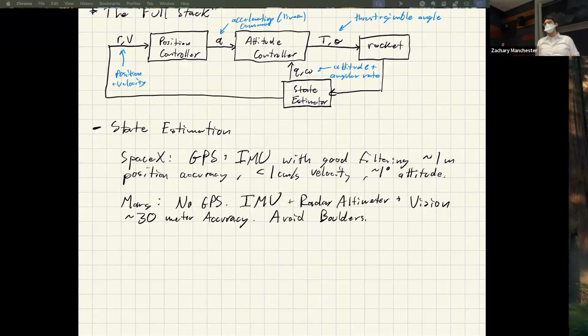As a result, the position accuracy you can achieve is highly dependent on the quality of your dynamics model and the quality of the measurements. So it's pretty tough. State of the art, by the time the vehicle gets to Mars, is about a kilometer when you hit the atmosphere. That's quite good, actually, if you think about what's going on there. But it's nowhere near what a GPS-like system could do, right?